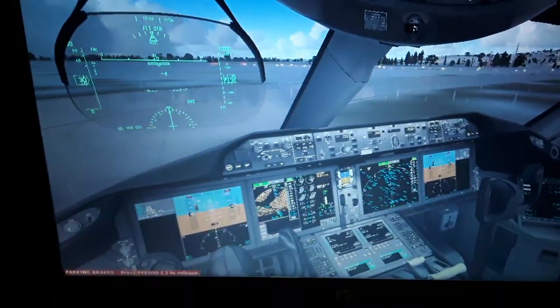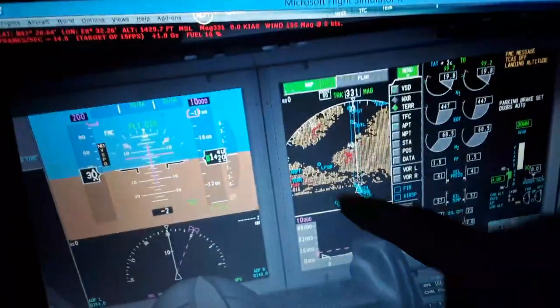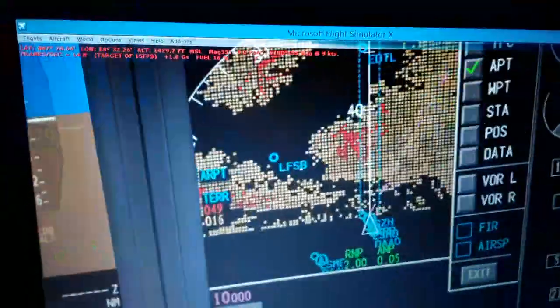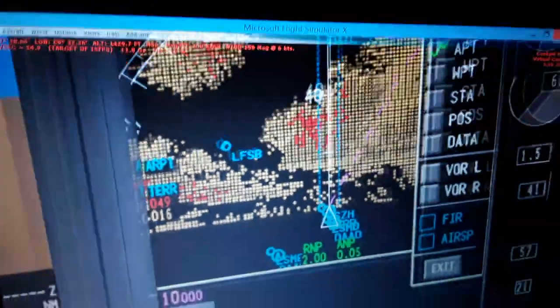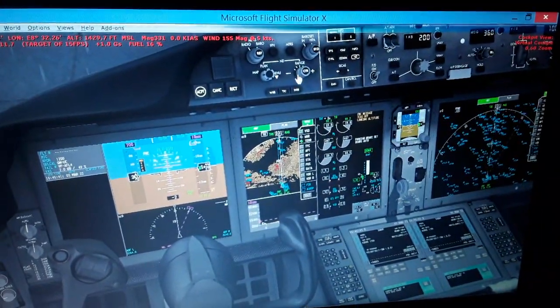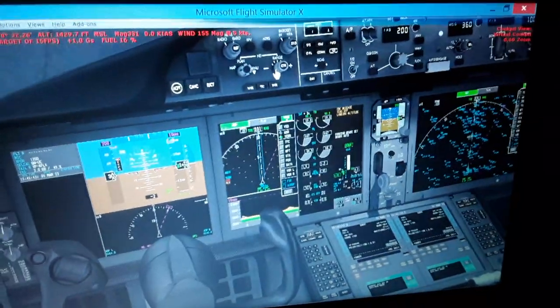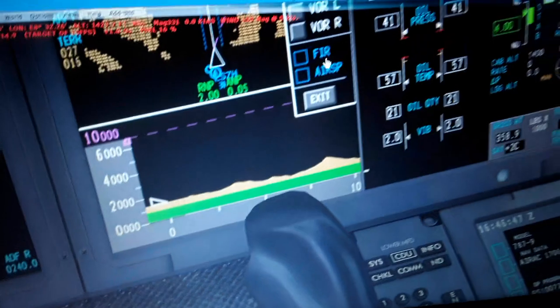The distance and also the elevation, whether it is higher or below you, will be shown over here. You can see in the navigation display different codes over here, red, green, yellow. As you can see, the red right now is 4,900 and the amber is 1,600. If we look closer, you will see when we fly we're going to have the terrain below us like this, and the distance. You can see the aircraft when it's flying.